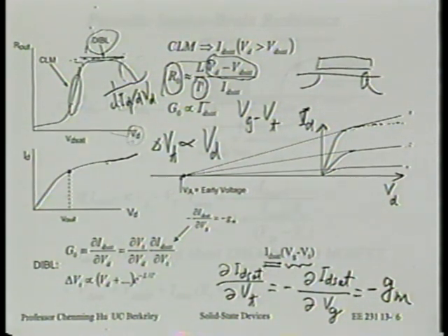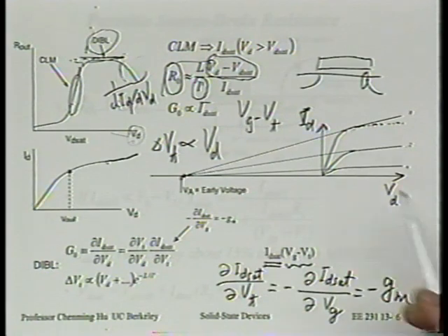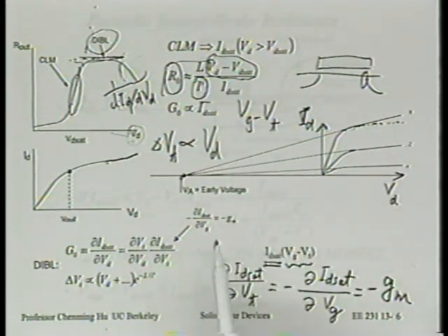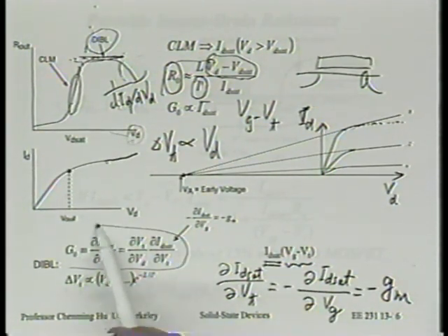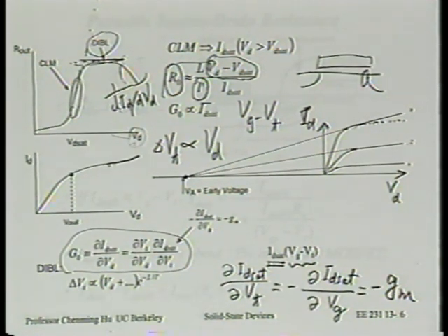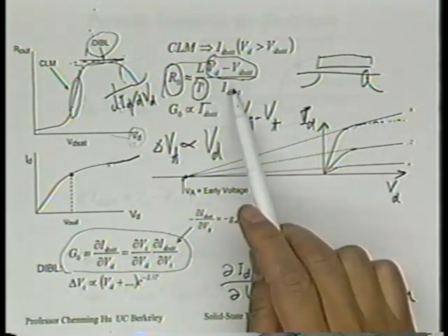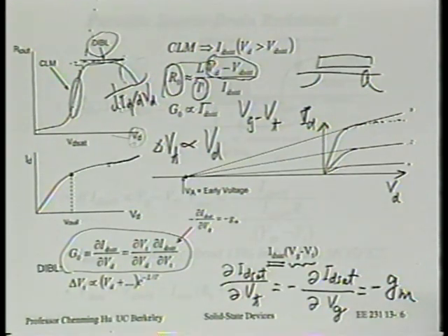Now this is a fact. This is not very useful from the physics point of view, although we can explain now why they have the right slope, because of this portion of that. By the way, this quantity, the output conductance due to the DIBL, I'll leave this as an exercise for the reader. See if you can prove that also roughly is inversely proportional to ID set.